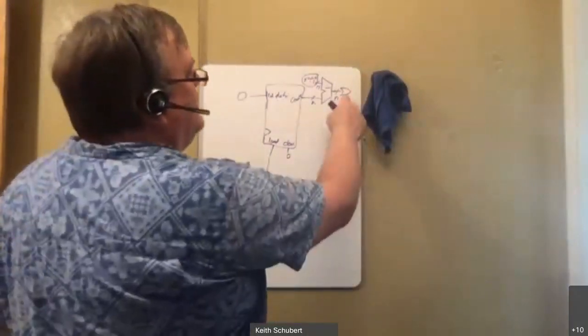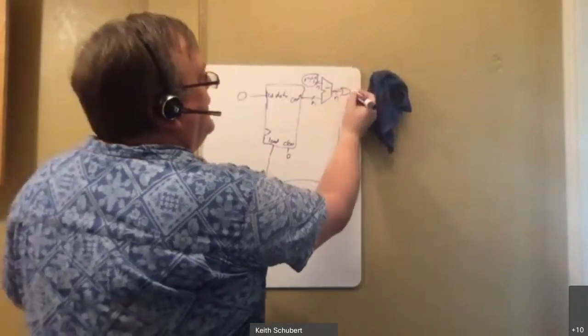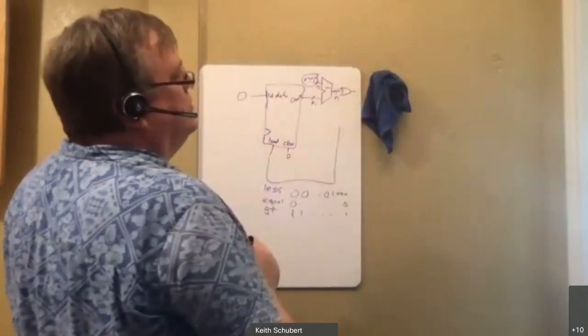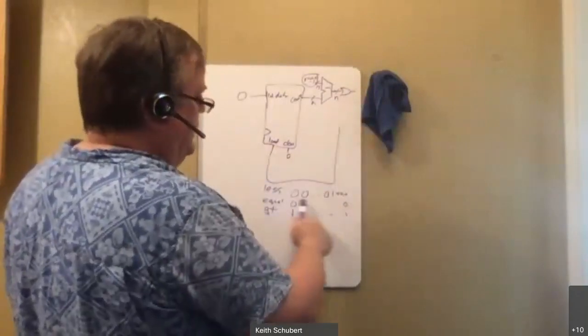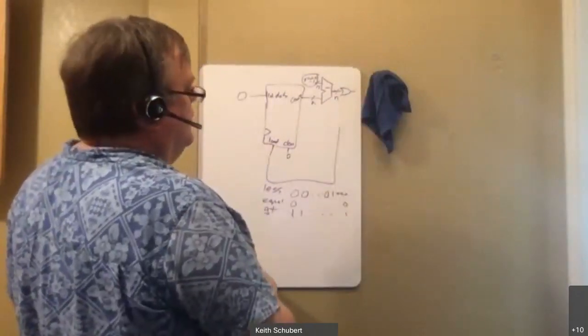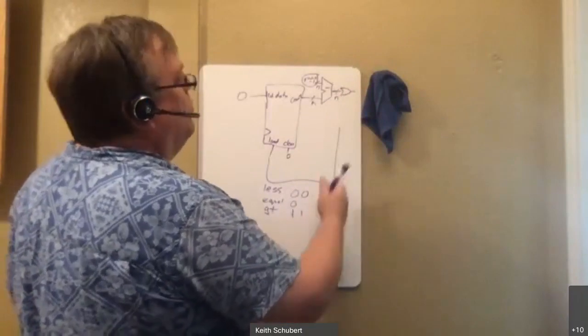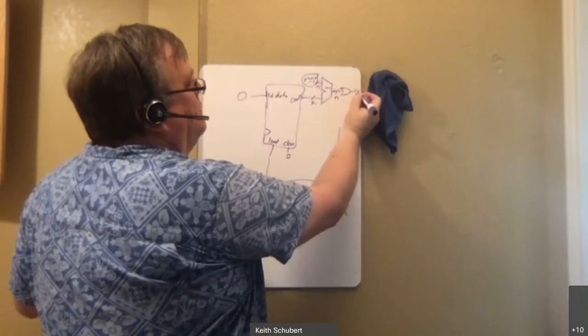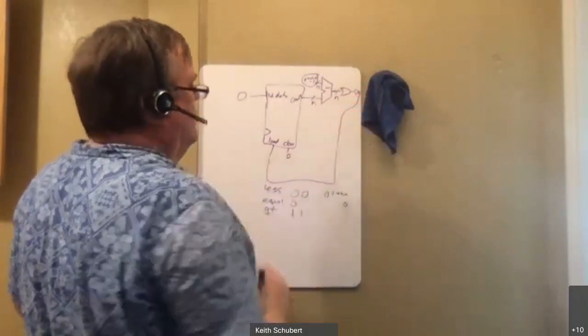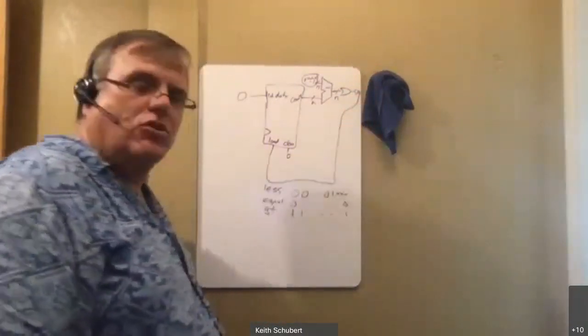The output of this is an OR gate with n inputs, but a single output. So the only time I can get a 0 out of this OR gate is when they're equal. Right, so I'll get a 0 when they're equal. I'm going to then take this and just invert it. And then I can hook that into low.